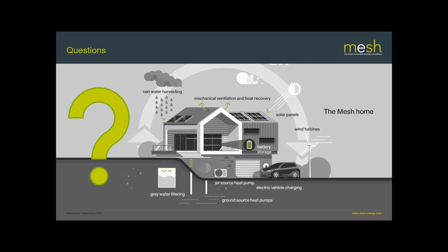Typically boreholes are about £20 a metre to bore. Obviously with smaller installations, the cost goes up a little bit, because you've got the cost of getting the borehole drilling rig to site and all the mobilisation costs. So it tends to be more economically viable for larger installations. And again, that's another reason why air source quite often comes up better on smaller installations.